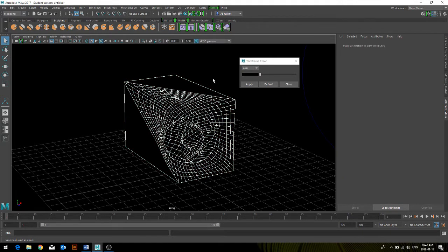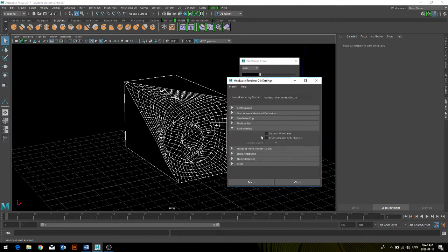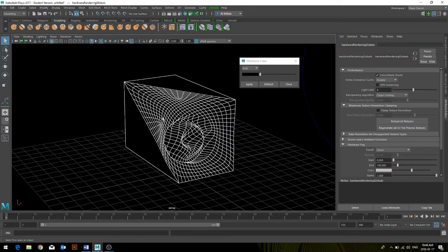And so we'll go into the render tab here, and if you go into the settings itself, you have to go under anti-aliasing, sorry. And what I found is in order to export a high quality rendering, it's worthwhile to bring the multi-sampling anti-aliasing sample count to its highest degree. And so this image is now ready to be exported as a PNG.